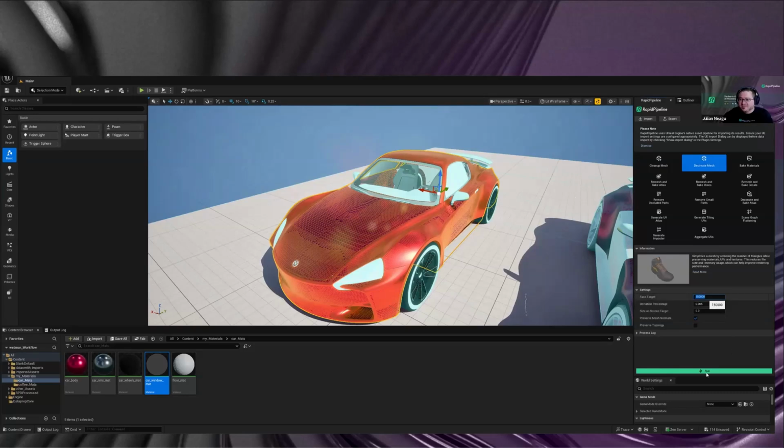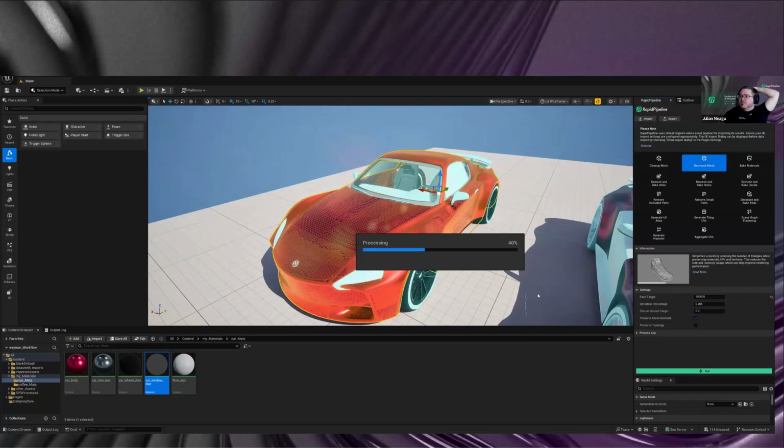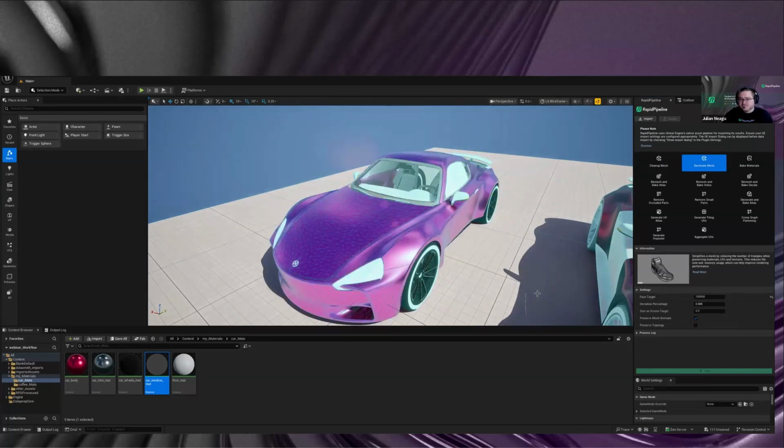Yeah, exactly. I think that was the resolution question. Triangle count we can go to. So in the finest tessellation resolution, in theory, you could go to custom and say you really want, I don't know, picometer, like 0 point something millimeter for the actual resolution deviation from the actual parametric surface. I would say open end. I don't think we currently have an upper hard limit on the triangle count generated. It really depends then also on the DCC, in this case Unreal, how much it can handle.